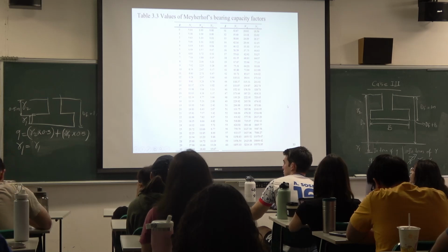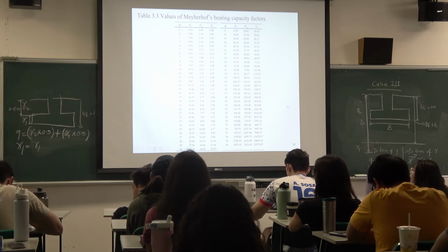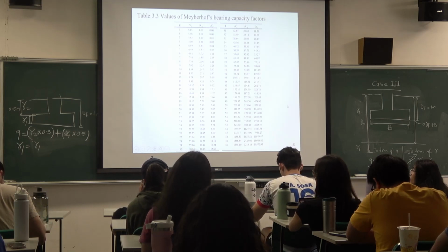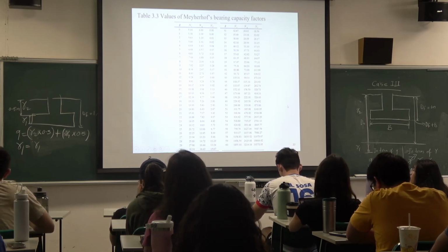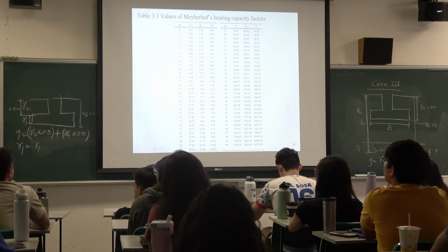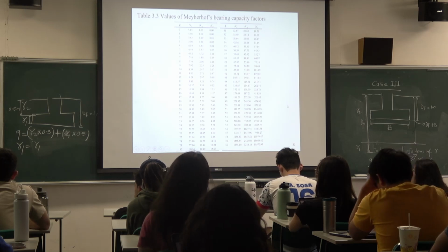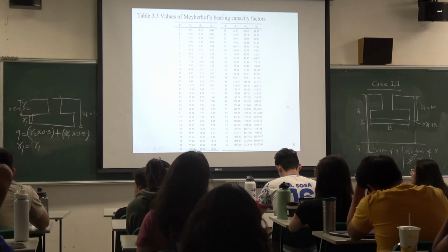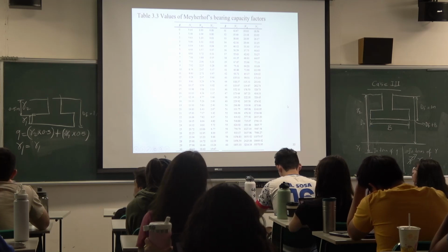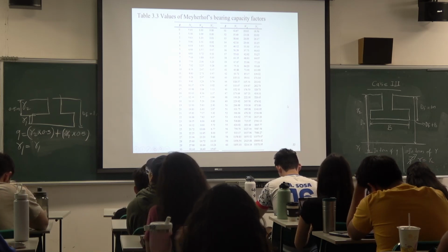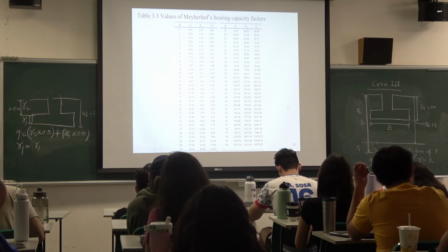For example, when they say dry sand, then you need to know that the cohesion is 0. In an exam, the professor probably will not give you that value. You should know that for dry sand there is no cohesion. They have no attraction, like the particles don't stick to each other. And when they talk about saturated clay that is mixed with water, the frictional angle typically should be 0 too. So in an exam, maybe they will not give you that value either. So those are two things that you need to know, the difference between the cohesion and the frictional angle.